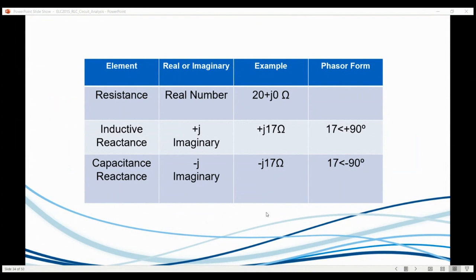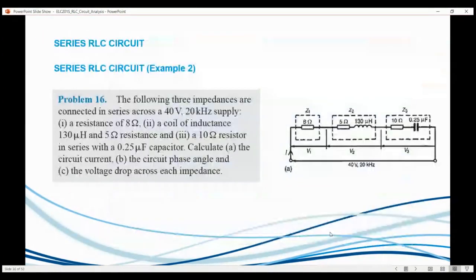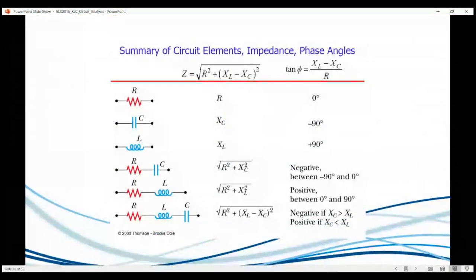Looking at this, again, where the plus comes from is essentially that angle over there. So that plus 90 degrees, that's in phasor form. I have the same numbers in phasor form. And the capacitive reactance is always negative j, whatever it is, ohms, and then that is negative 90. So that feels not very intuitive because one is leading and one is lagging. But nevertheless, that is the representation of how it must look. Okay, cool. So we did that one, we did this one, and this is also a